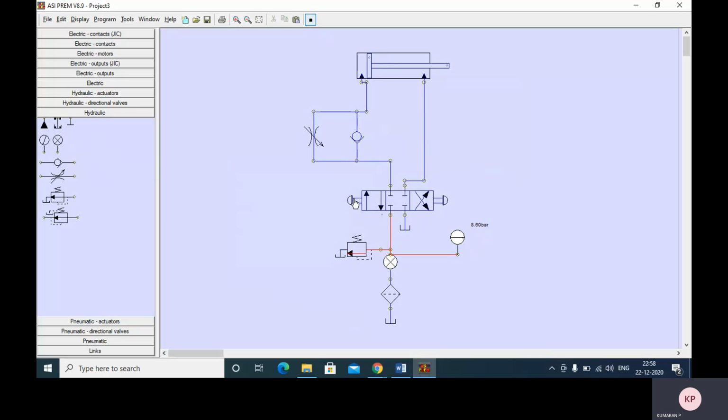By means of engaging this straight position, piston is moving forward. If you leave this, I want to retract, right? So same speed it's working because 10 bar pressure fluid is going both the side.